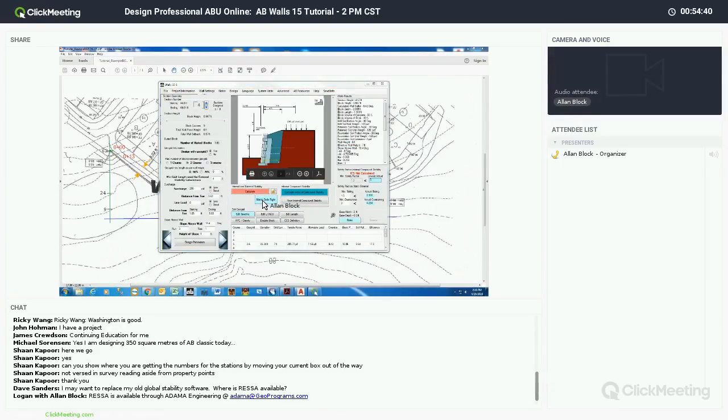See, pretty standard. All right. Now, looking at this, I've got 2 course spacing at the bottom of my wall, but I have 4 courses at the top. You have the choice to leave it as is and try and analyze it as a complex composite structure, which is a totally different tutorial that we do offer. But right now, I'm going to add a layer of grid.